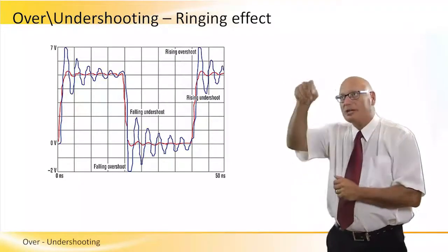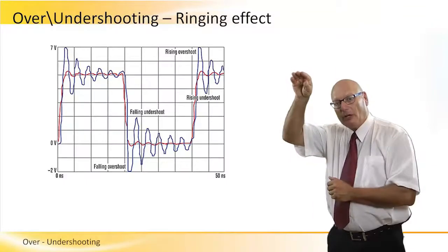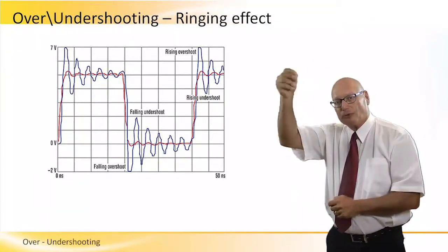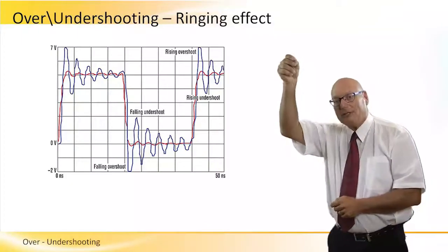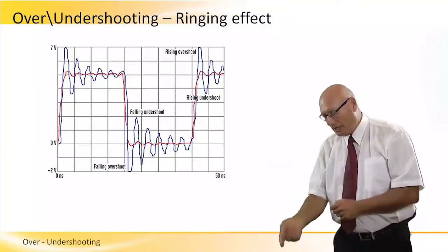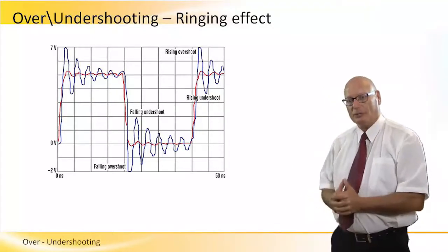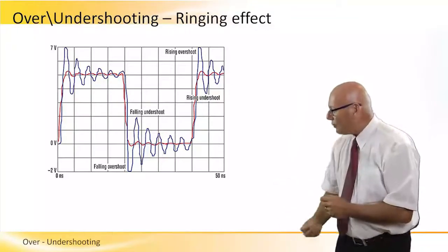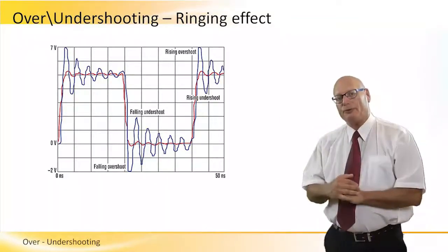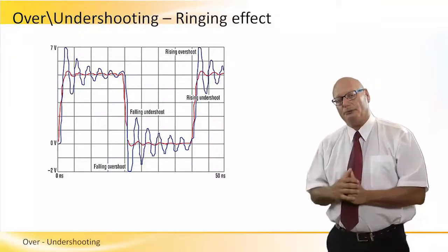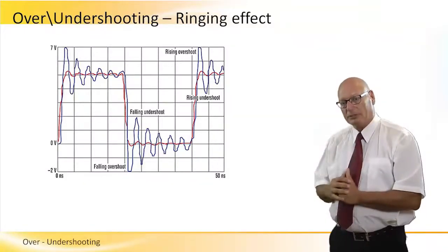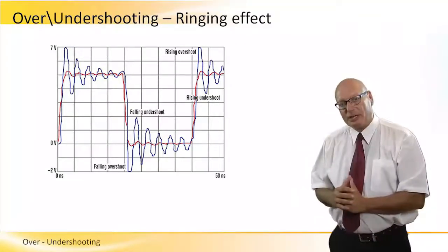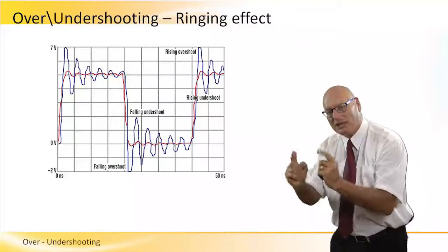It goes up, has overshoot and undershoot there, and when the time comes to go down, even if we have overshooting and undershooting there, we are actually taking it down, and this is being accumulated. We can see that when we go down, the amplitude of the overshoot is bigger than the amplitude of the overshoot when we go up. Very easily we see that the overshoot, undershoot, the ringing effect takes the entire resting time.